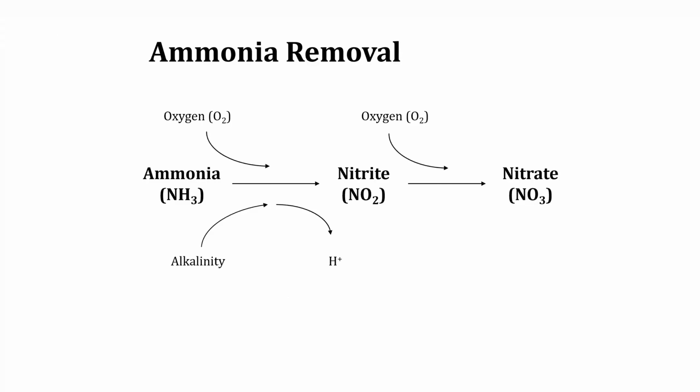So ammonia removal looks something like this. Start out with ammonia, and then all these H's get exchanged for oxygens. All the hydrogens go into solution. That's what chews up the alkalinity. If there's not enough alkalinity, we'll actually drop the pH. Otherwise, my analogy, it melts the ice cubes, gets rid of the buffering capacity, if that strong buffering capacity exists. Requires a lot of oxygen.